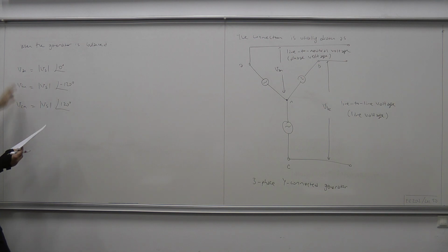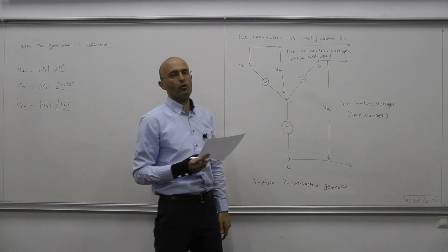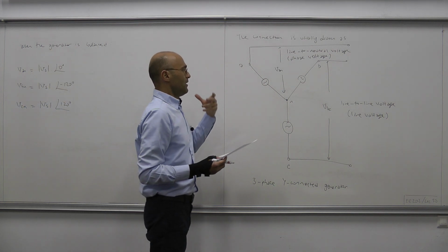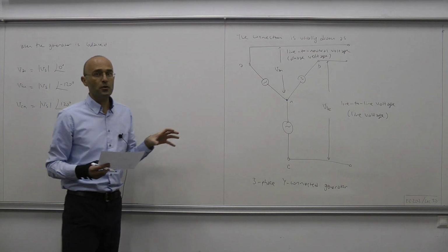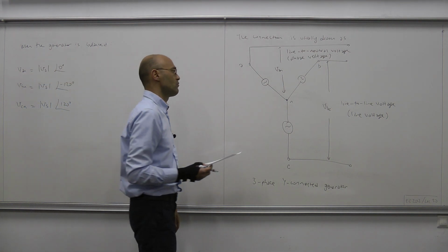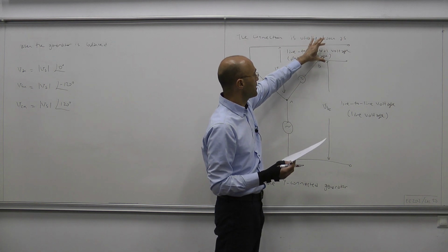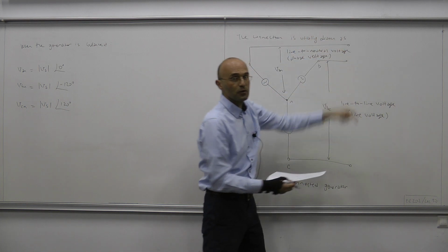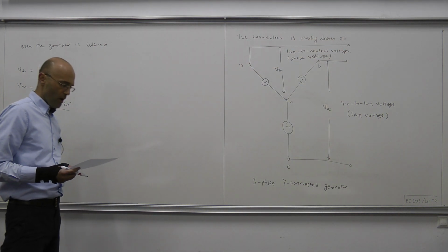Okay, now these are the voltages, our balanced set, and from these phase voltages or line to neutral voltages, now let's try to obtain the triple that's associated to line-to-line voltages. Namely, let's obtain VAB, okay, the voltage drop here, VBC, the voltage drop here, and also VCA, the voltage drop between the top and bottom lines or the wires.